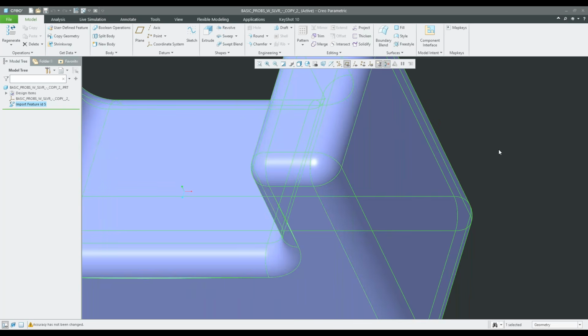Should you check the fixed tangency box when repairing? You can check that. Just make sure that only the surfaces around the area that needs to be fixed are activated first, because if you don't, and it's trying to create a fix with tangency on the rest of the model, you'll start making changes that you might not want to be changed. But yeah, you can select that.